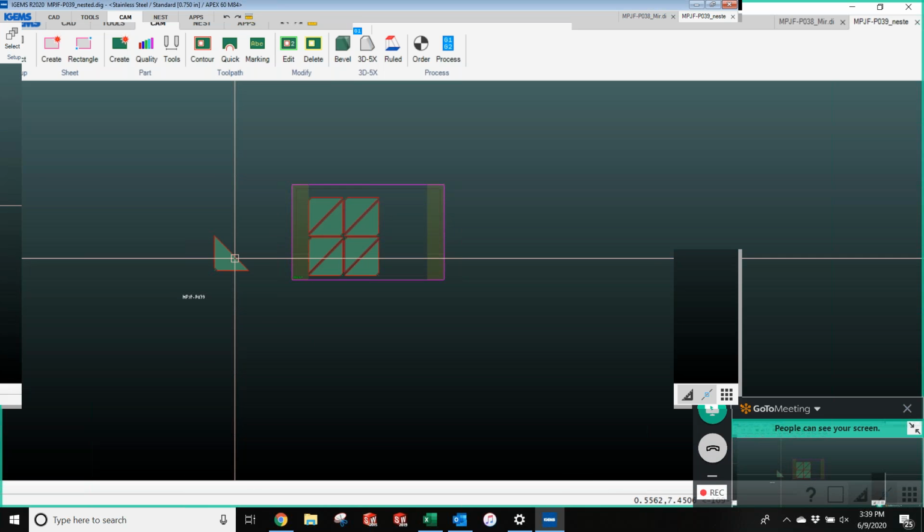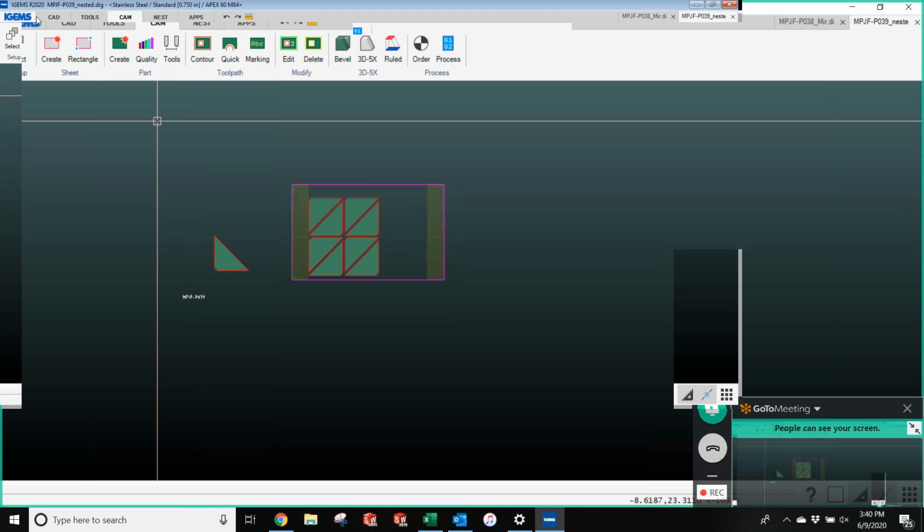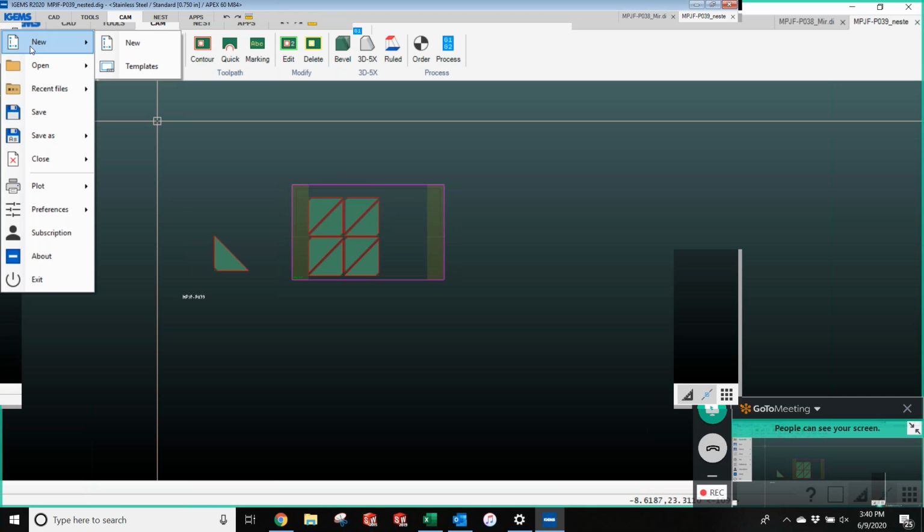So I'm not trying to make this machine take the place of a milling machine. But the closer I can get to 90 degrees at some points when I'm putting together different fixtures or different components, the better off I am if I need to flip a tab up and drill and tap, right, to bolt it to another plate. So I wanted to at least learn how to move it. If I had to, I'm assuming I would need to cut a test part till I was satisfied with the way the cut works, and then determine that's a good taper comp and run the real part. Right. Yep.